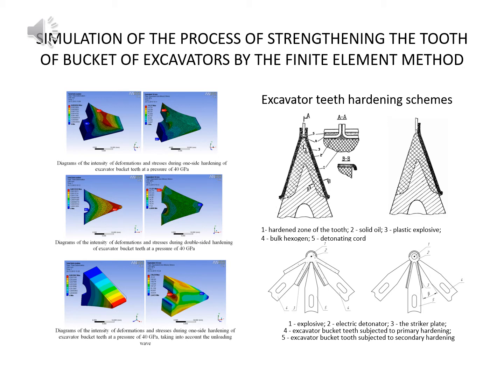The factors affecting the degree of the explosive hardening include the applied pressure, the duration of the impact pulse, the nature of the loading, and the velocity of the linear pulse. For explosive friction hardening, the factors are the same as for explosion hardening, only instead of the linear impulse velocity, the velocity of the friction material is used.